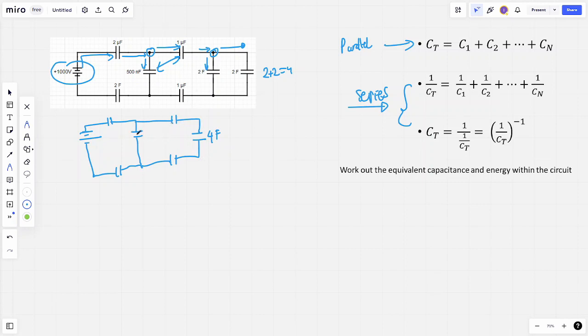Now if we look at current at the right hand side, away from the power source, which is a really good place to start, once the current splits at this node, either current can go straight as discussed, or it can go down. So if the current here, let's just call this current X, can only go in one direction in this loop, which is around, down, back around. So therefore these 3 capacitors are now in series.